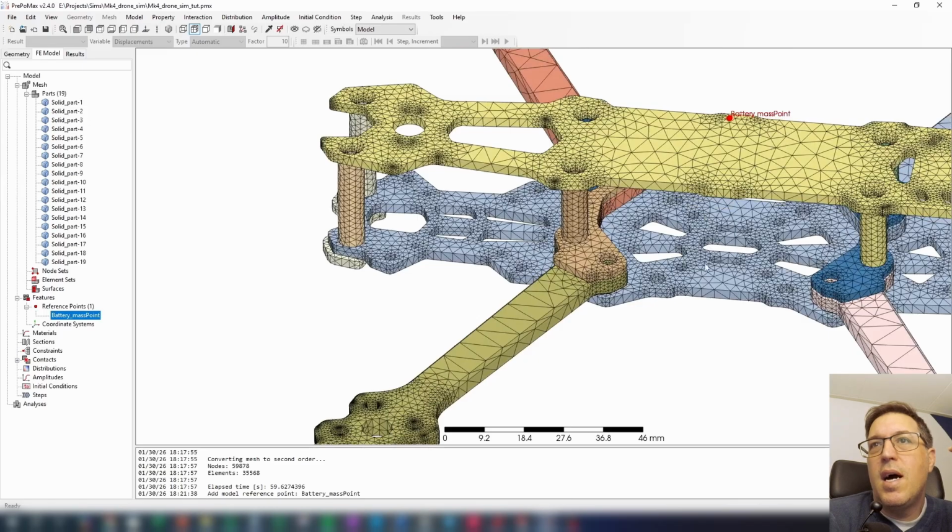And again, I'm less interested in this area for the analysis. I'm interested in the natural frequency of the system and how those bending forces are going to be on the arms. And this is an assumption at this point. My assumption is these are the areas where we're going to see higher loads. So let's start by creating surface names.